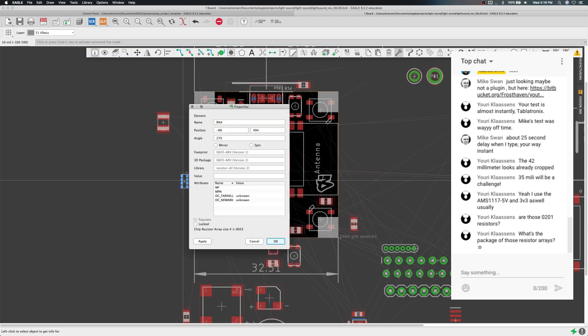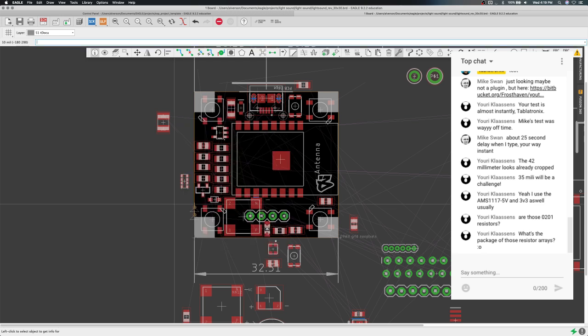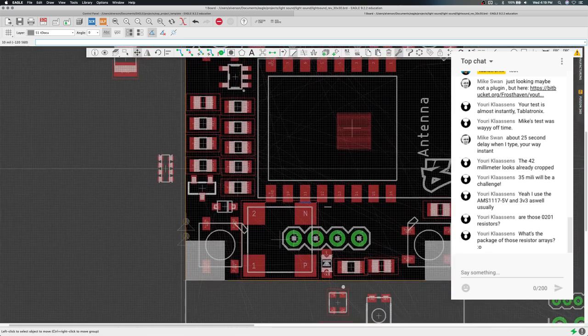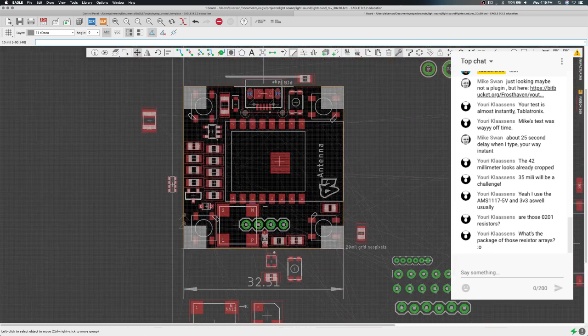But it's actually a single package. It's 4 resistors in one package. And the one package is the size of a 1206 component. That's a 13, but yes, you know what I'm saying. But they're tiny. The leads are tiny. I mean, that's 10, 20 mil, maybe. So hand soldering, that's kind of problematic.